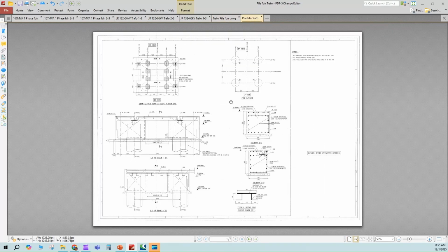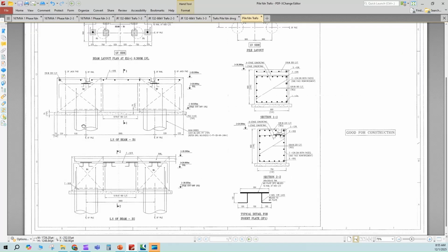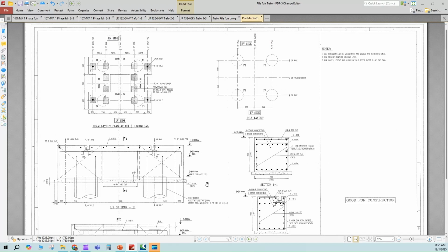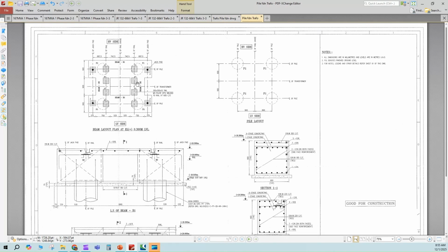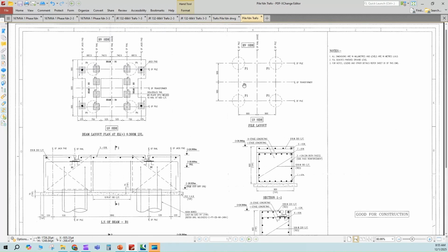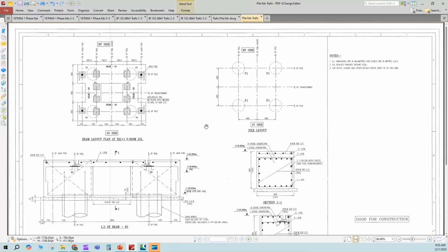And finally we are going to look at pile foundations. This is a cast in situ pile. Over that the pile cap for the transformer is placed. So this main block for the transformer is done with a pile cap. The remaining oil bund and slabs are done with masonry works, so those details are not shown here.